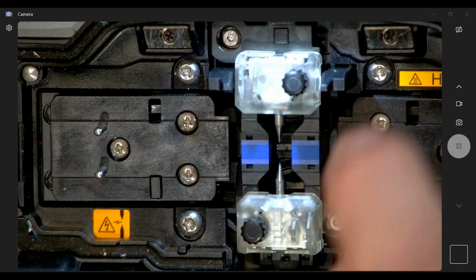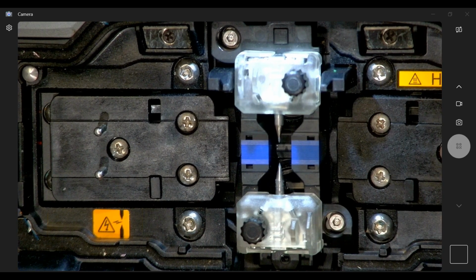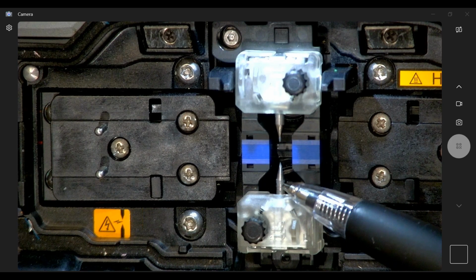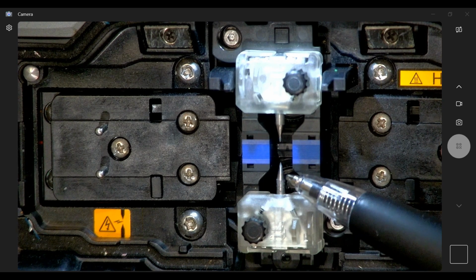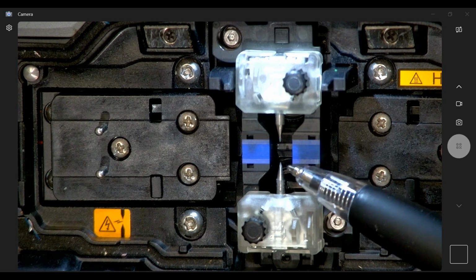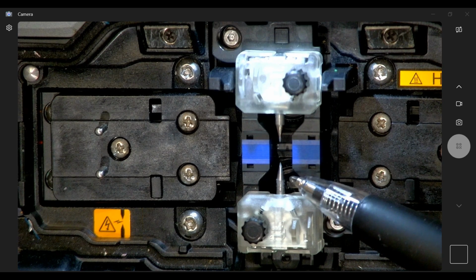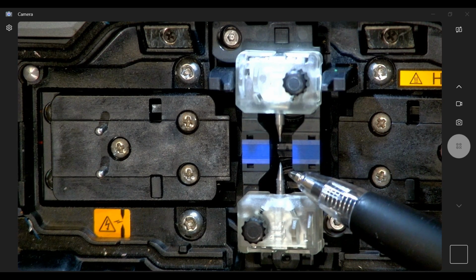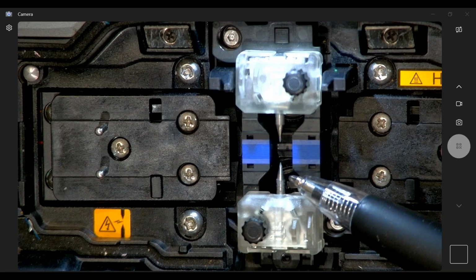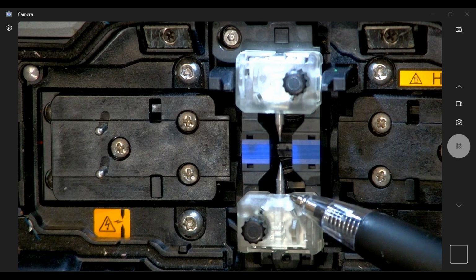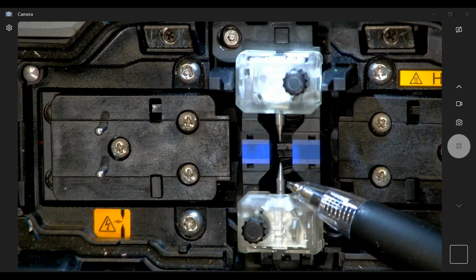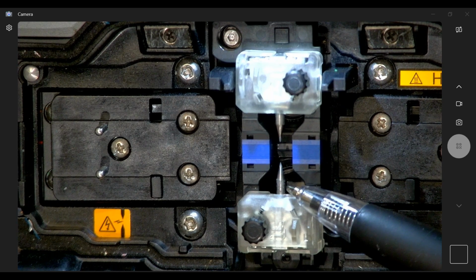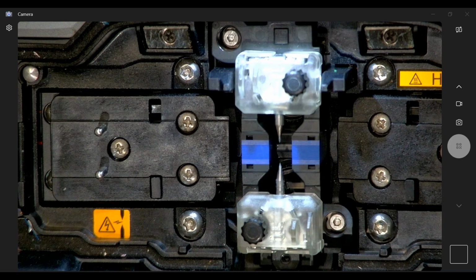Of course, when you put in new V grooves, you will want to stabilize your electrodes. And what stabilization means is, if you look at these electrodes, it's probably going to be a little bit hard to see them, but they are kind of white on the tip. This is where glass has been vaporized and the silica oxide is on the tip of that electrode. It happens very quickly, but if you replace the V groove, you want to stabilize these electrode pins to get that silica oxide in place, and then you would do an arc calibration from that point to get ready for the next splice you're trying to make.